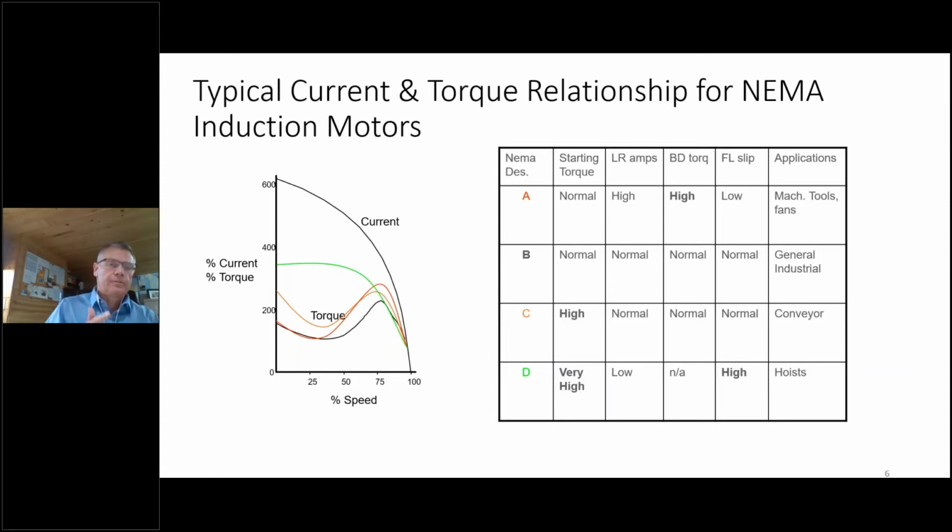So if you have 10 large motors all being turned on at the same time, you can get a flicker situation, or even a complete blackout where you overtax the grid or the transformer and it goes into a shutdown. And if you haven't been around this concept before, you will see it happen many times in all of our commercial buildings.